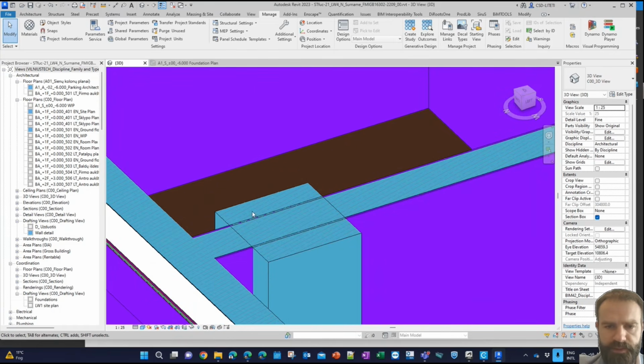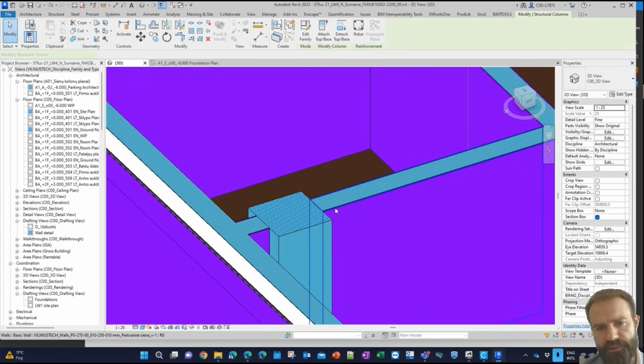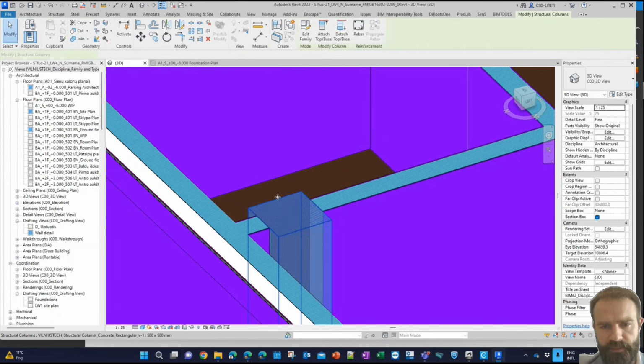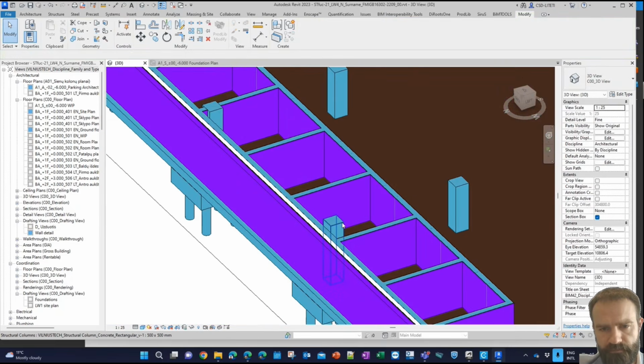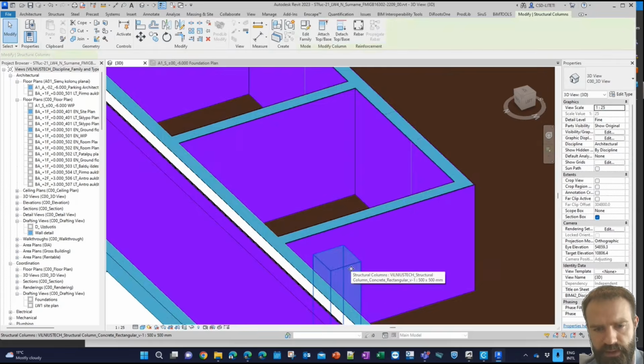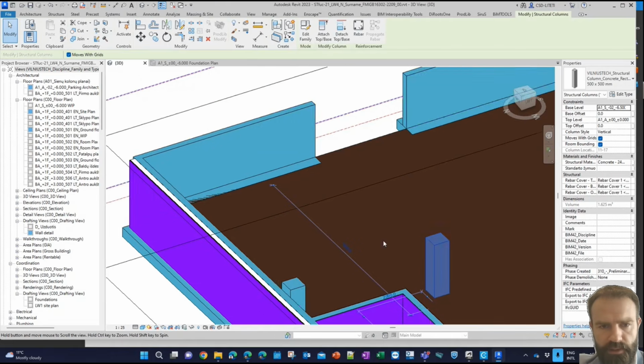Another problem with columns and walls, we have this kind of situation. So to solve this kind of situation, it's best to split wall into two parts and just use extend tool and just move one wall and another wall to another position. So walls and columns should be separated. And it should look like this. I still have double columns here. Okay, one column, double column. Okay.